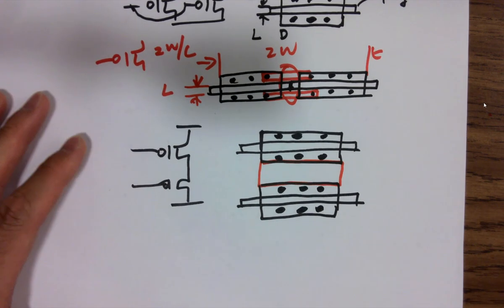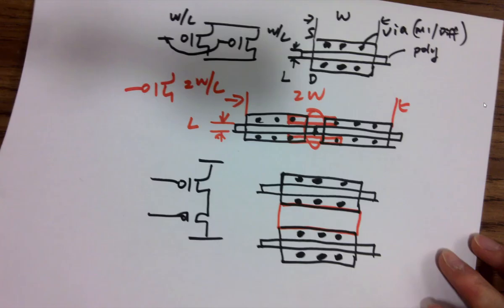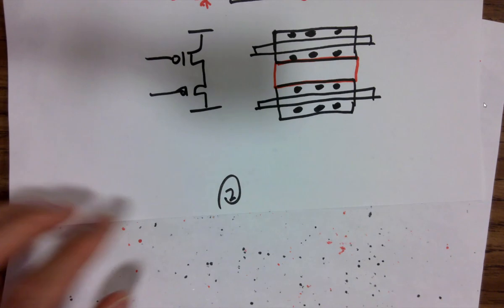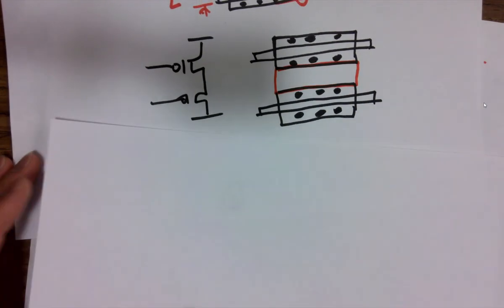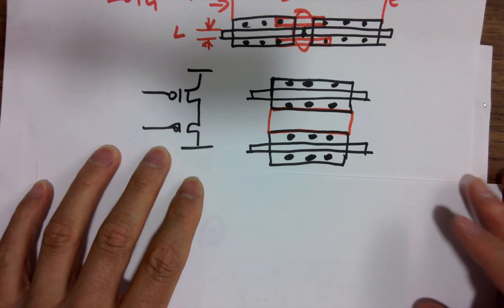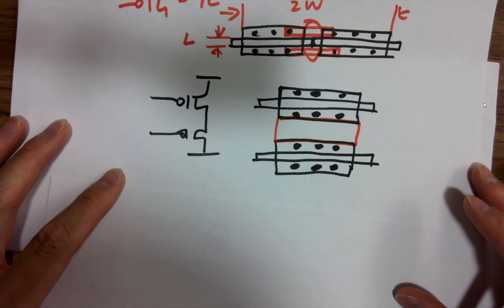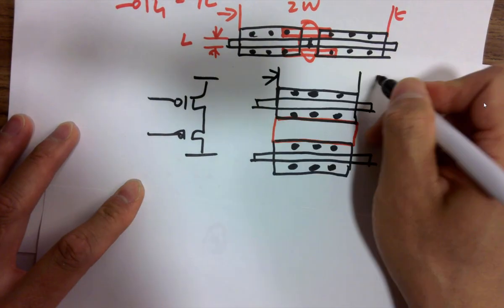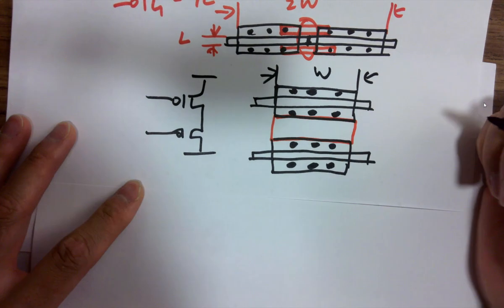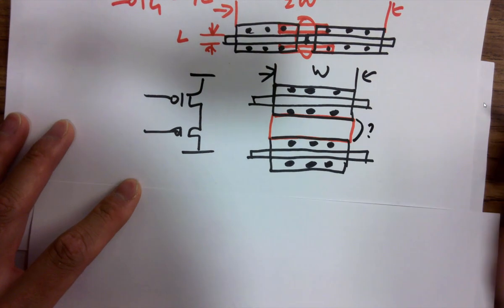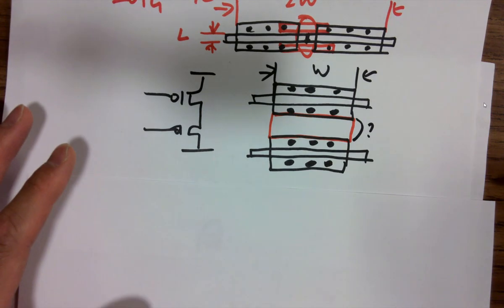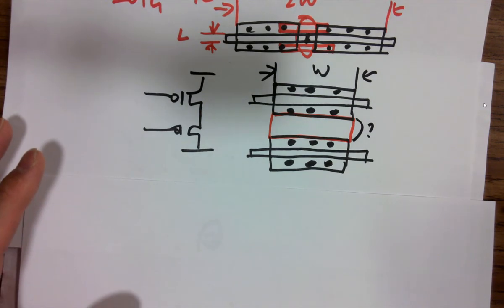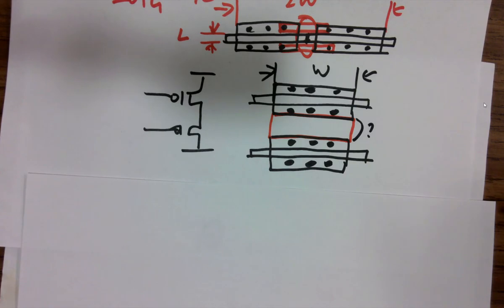Can you simplify this? It's just taking too much space, and we're trying to optimize it. Are you changing the width? Is the width being changed? No. What about the length? What about here? That's just metal. Ideally, we consider the vias as metal, and it's metal one. It's just one voltage node, so it doesn't matter how long it is. We consider it ideal. It's just one piece.